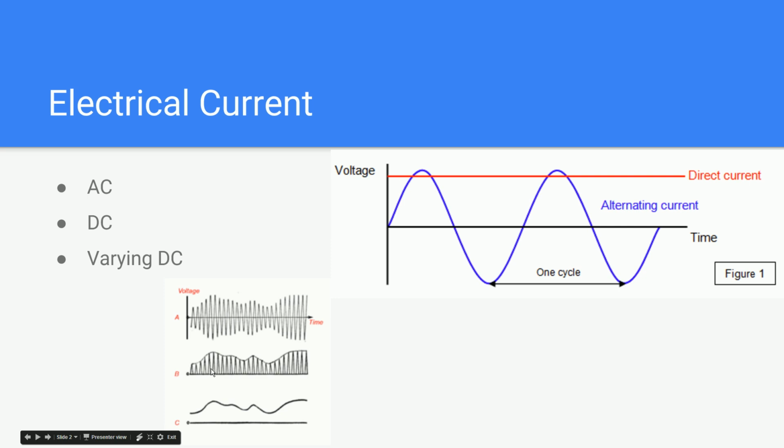When it comes to the radio, they tune into that signal at that frequency, then they chop off the bottom half through a process called rectification, so then you have this changing DC current riding on top of the AC waveform at 550 kilohertz, and then they get rid of the carrier wave, so you're left with this changing DC current that you can run through, say, a speaker or headphones or an amplifier.